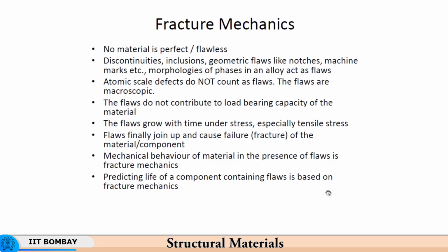So, final failure in the form of fracture would take place if the flaws were to grow over a period of time of service, if they were to coalesce and then form a crack and finally snap into two. So, the life of the component would be the time duration that is needed for the flaws to grow.